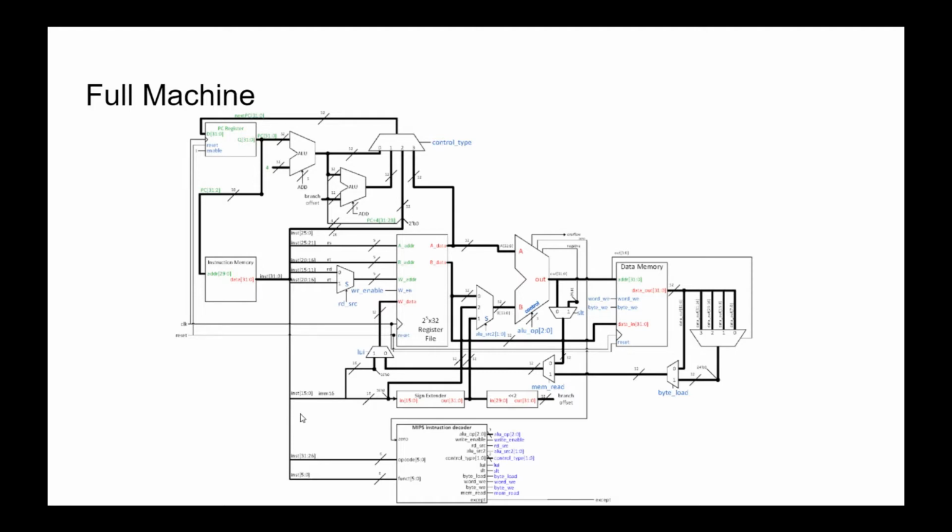So instead, we take the 16-bit immediate, we sign extend it, and then we shift it left 2 positions, and that's happening down here. And this is why we built a half sign extender in the previous part. This is exactly what it's for.